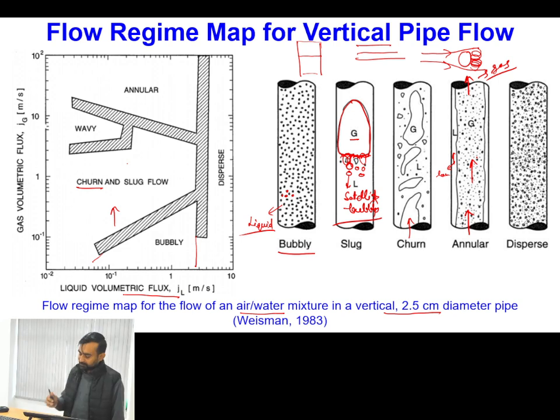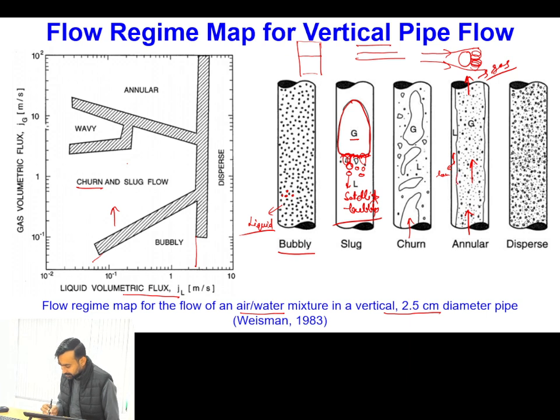Okay, and whenever this gas is moving at high speed, any perturbation at the surface of the pipe, if it reaches the critical regime and grows further, there may be growth in its amplitude, and one lamella of liquid will be generated, which will then finally pinch off in the form of small droplets. So typically in the annular flow regime, we have a combination of both liquid and gas, and inside the gaseous core there will be a large number of droplets.